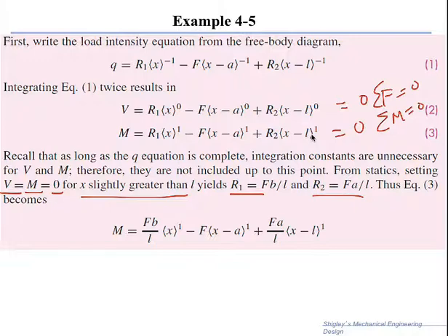And note that anything raised to the power 0 is equal to 1. That is exactly the same as saying that F is equal to R1 plus R2. And then the sum of the moments equal to 0. This is the moment of the reaction R1 when you put x equals L, and this is the moment of the force F, and this is the moment of R2.